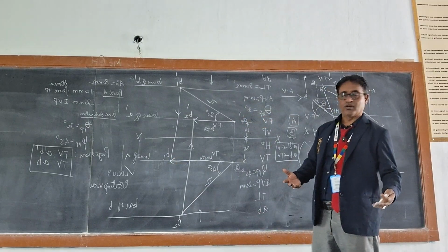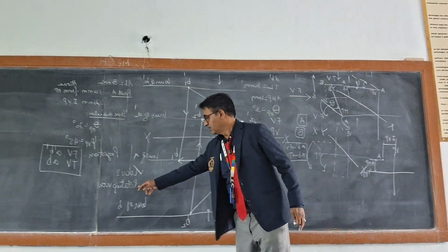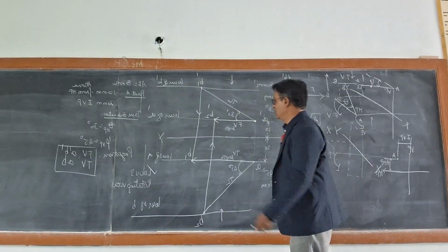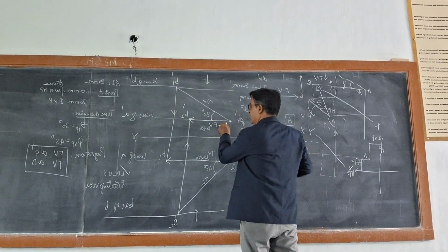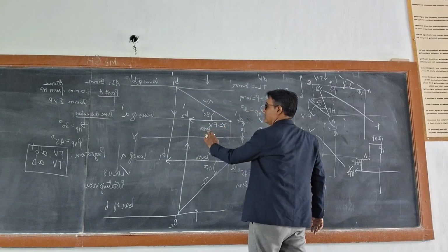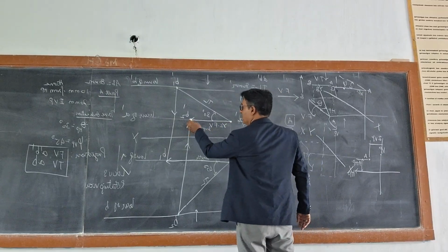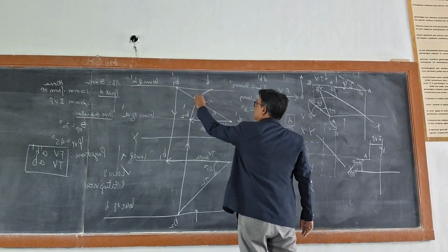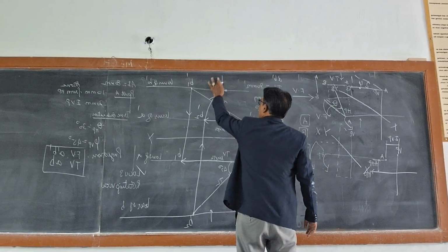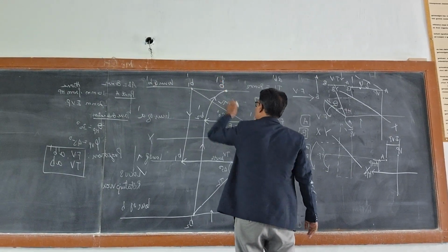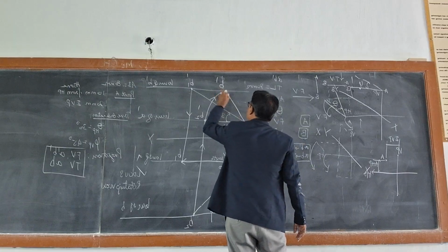Now, what I am going to do is rotate the views, right? I am going to rotate, say, with A dash as center, radius equal to the front view length, which is nothing but A dash B2 dash. Draw an arc that will be intersecting the locus of B dash. That point is called B dash. Now join this A dash with B dash.